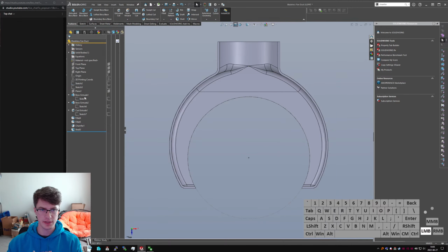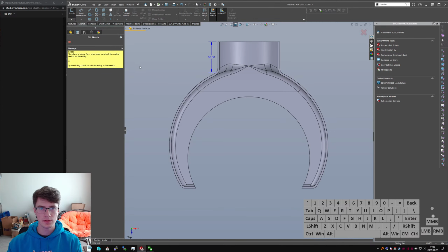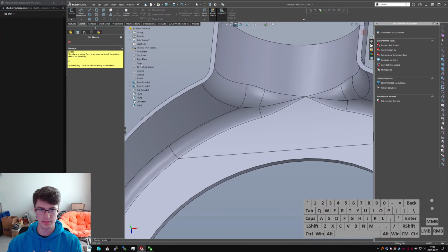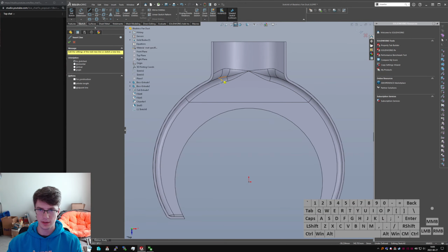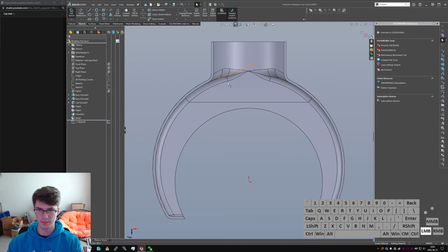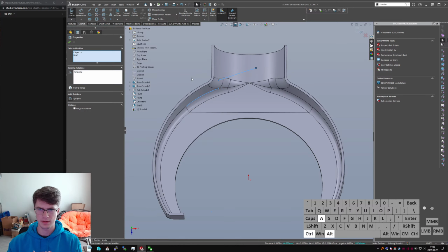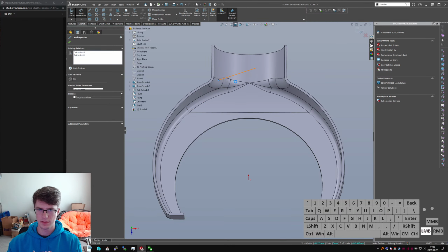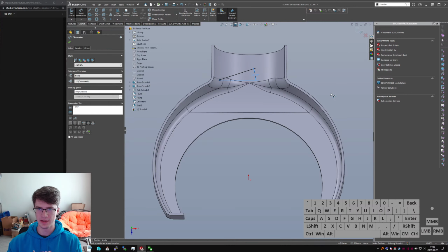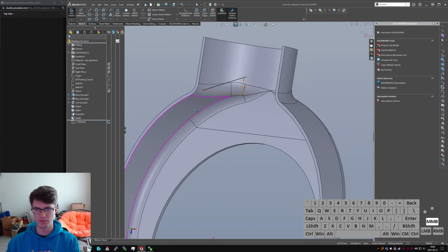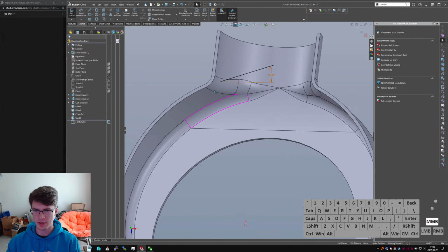Hide the other irrelevant sketches. Shift C to hide everything. So over here, we get a little bit tighter, but if we come to the top plane, a quick check on our maximum angle. Let me pick that. Our maximum overhang angle in here is 72 degrees. I can quite comfortably print that in PETG, so I would have zero fears about printing this thing. It would come out quite well.